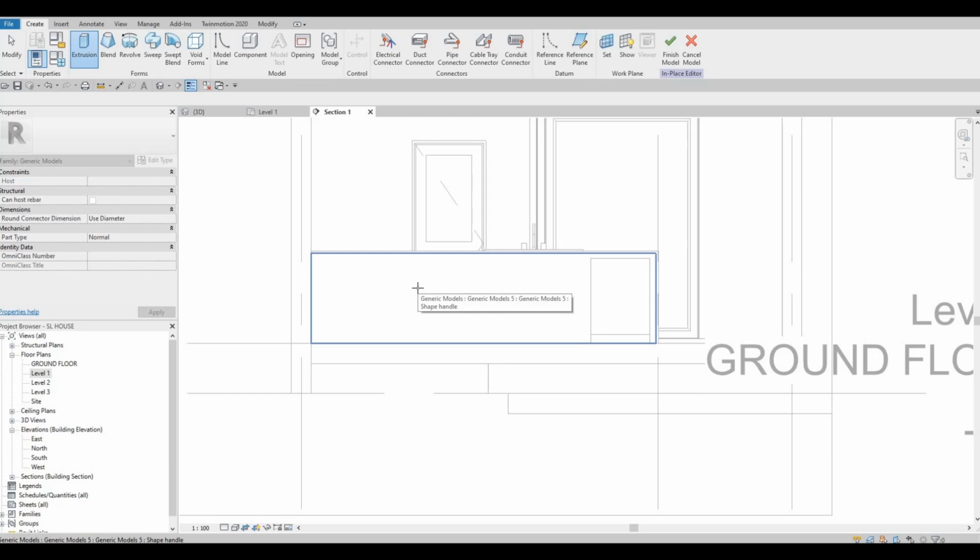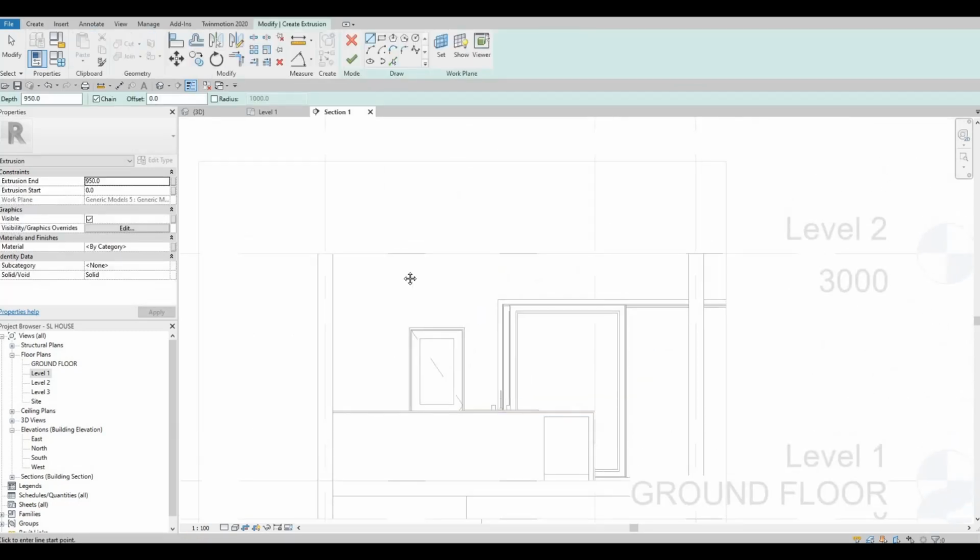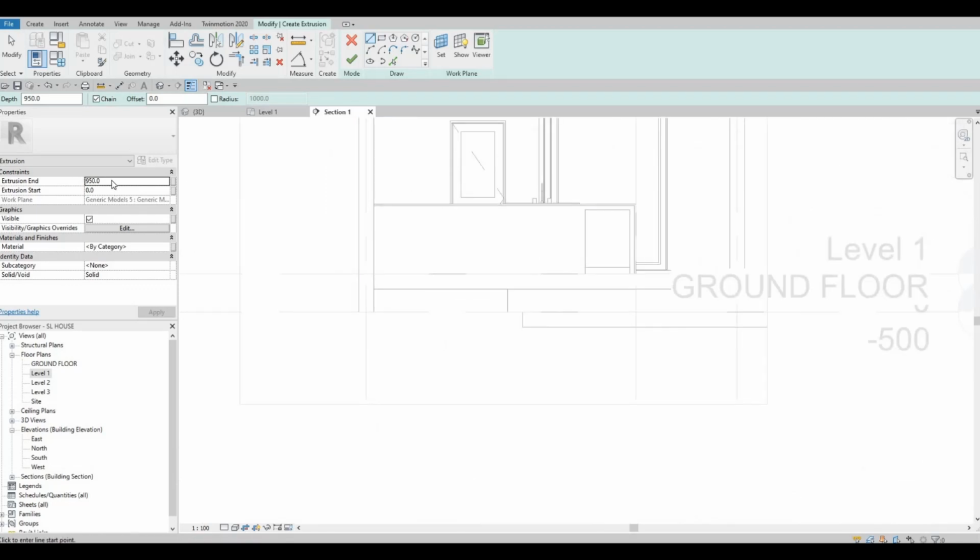That's the indication that this is the face for the front, where you place your section. So now make sure that this is 25, or else it's too much extrusion, but you can always pull it back. That's how easy it is to use model in place.